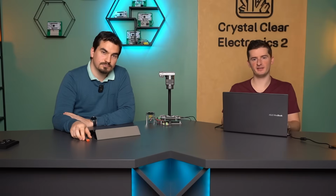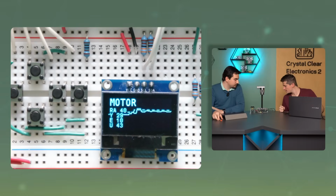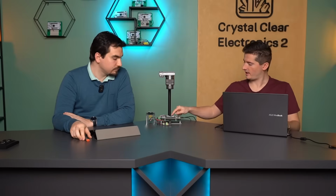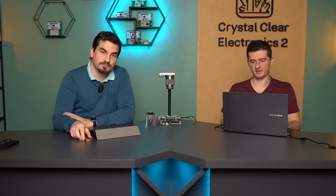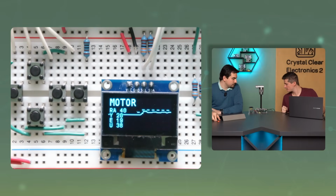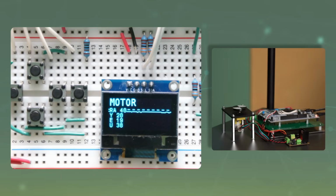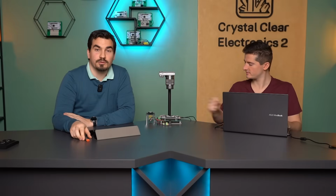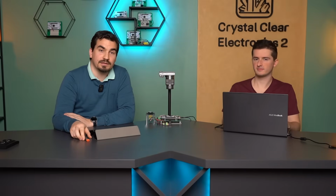Let's give it a try. Take the originally set value of Kp equal to 4 with a set point of 40. The shaft rotates at about 28 RPM, which means 12 RPM is the residual error. Change the Kp value to 2. Now let's see what happens when we set the set point to 40. So now the shaft is only rotating at about 20 RPM, which means that the residual error has increased to 20 RPM. The question may arise, how can we find the right value of Kp?